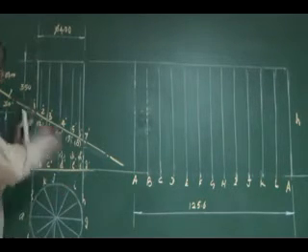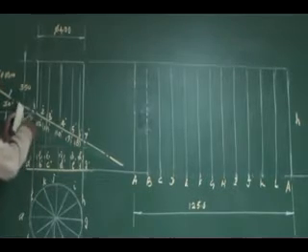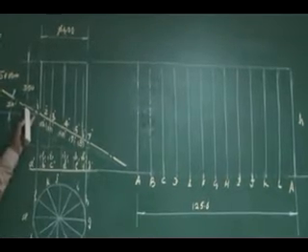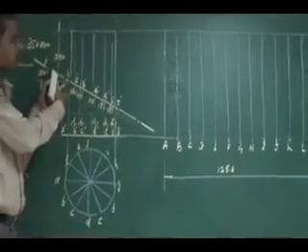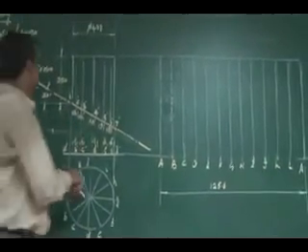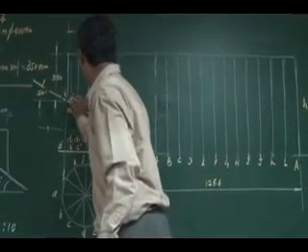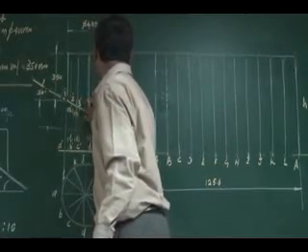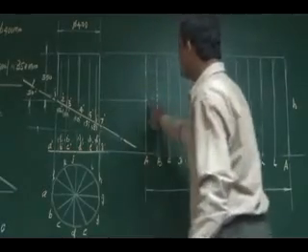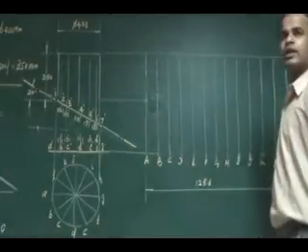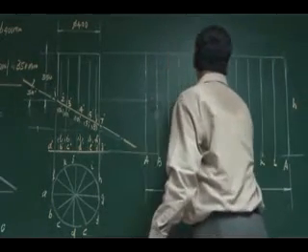So then I have the cutting points, 12 cutting points. They cut 12 generators. So you see the cutting points in a sequence you have marked. So cutting point 1 is on which generator? A. Cutting point 1 is on A. So directly I can project this cutting point as usual, something like the prism, how you have shown in the last problem. Just project the cutting point 1 to the projector, generator A. Similarly the same location is there in your development at the other end. So that same A will be projected.